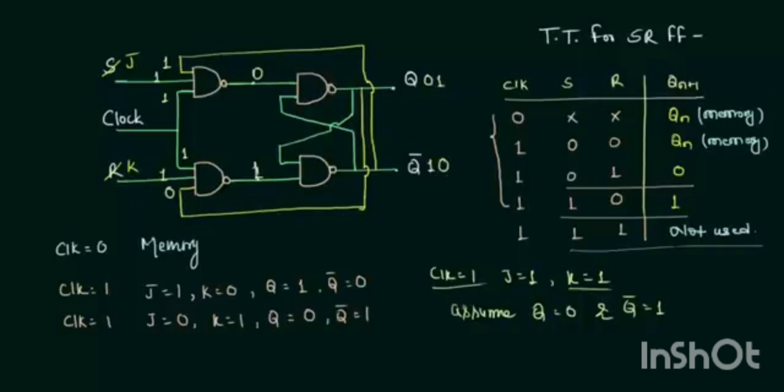Okay, now you can see that the output is changed, so the input will also change. Q has become 1, so at this point instead of 0 I'm having 1. Q complement has become 0, so 1 will become 0 here. Now 1 and 1 and 1 will give us 1, and taking its complement I'm having 0 here, and 0 and 1 is 0, and taking its complement gives us 1. So this 0 will become 1. Now when this happens, we are having output as 0, 1.